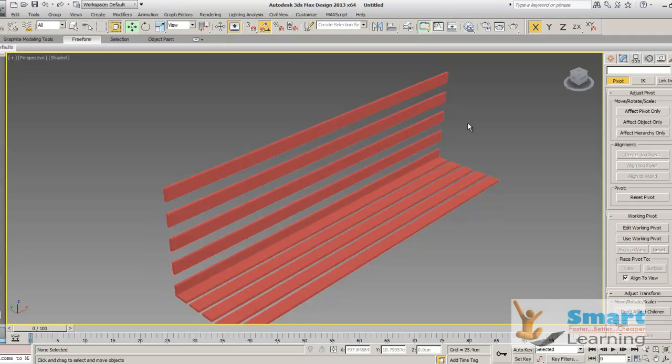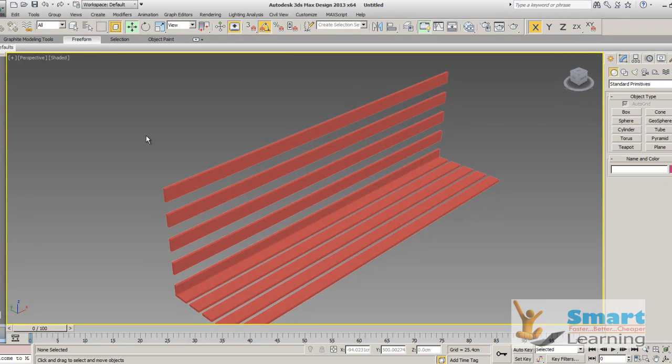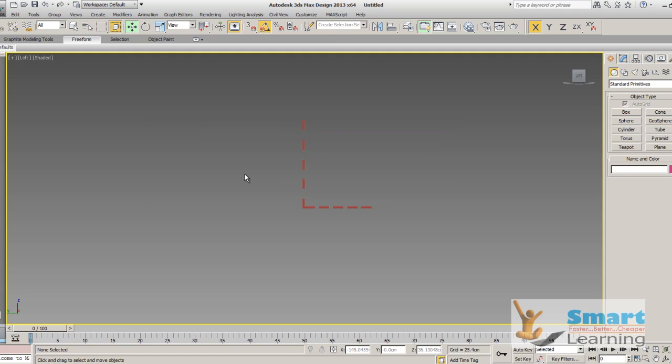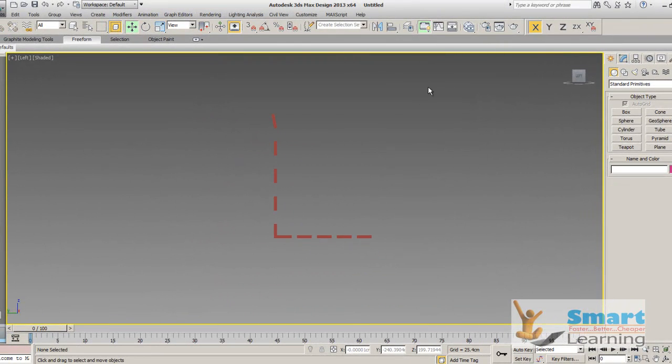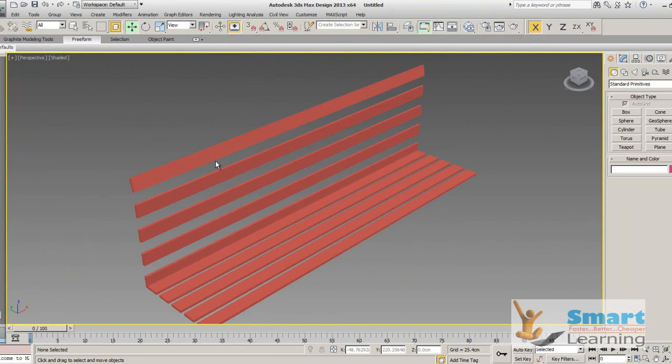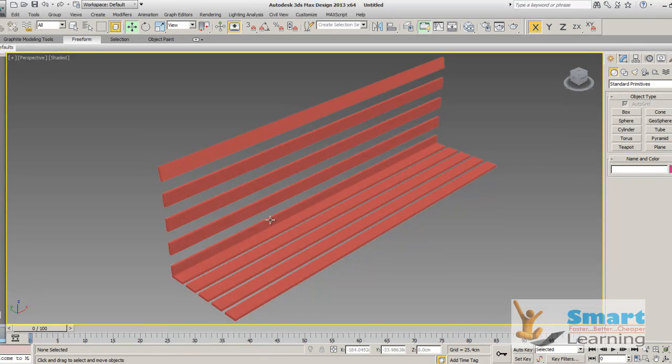Now whatever the top little bit rotations I'll be applying, so I'll go to the left side view, I'll select this top one, and I'll go to rotate, and little bit of tilt. I will switch off this angular snap, little bit of tilt I will apply, and I will move little bit left side to position this perfectly. So this is the initial skeleton which we have created in line with the requirement. Next we will create the frames where this complete stuff will be positioned.